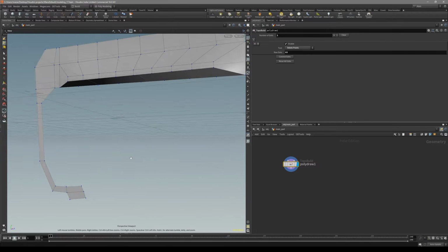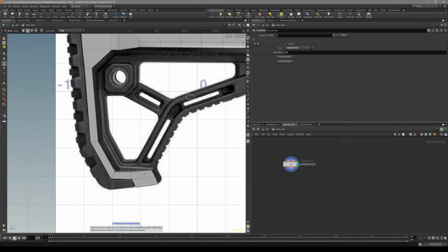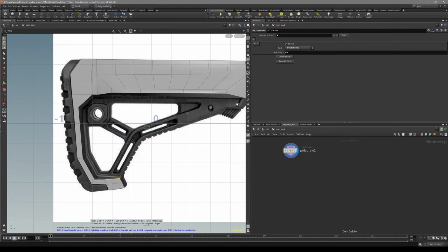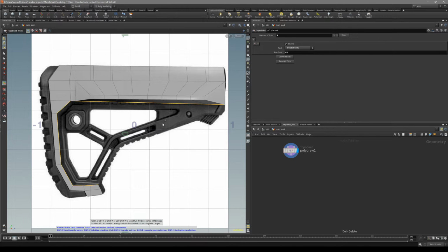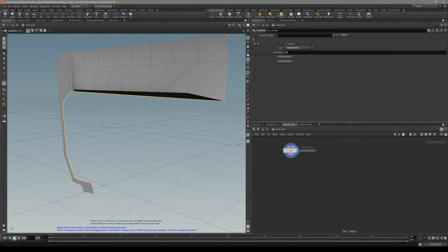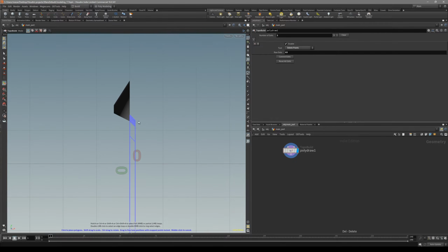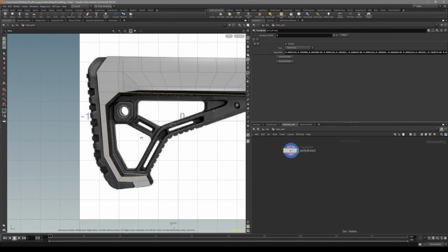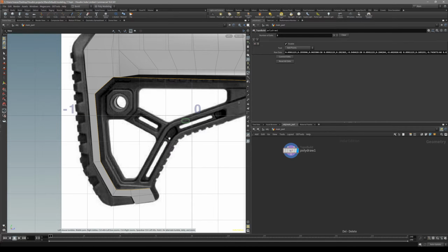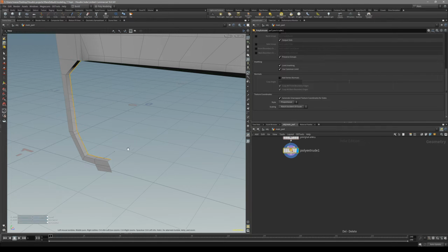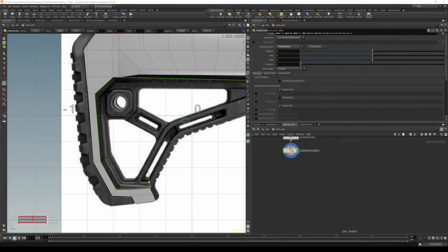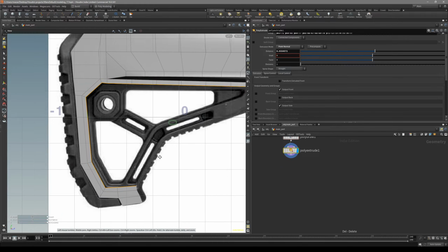Now let's start with extruding this inwards. So in the picture you can see it's basically, now let's extrude this inwards. So just in polytopo build, just go inside, select these, and with control limit the axis and like that, and now we want to extrude it inwards. So for this, just select the same edges that we just have and then extrude it, and put down extrusion mode to point normal so that it goes like that inwards.